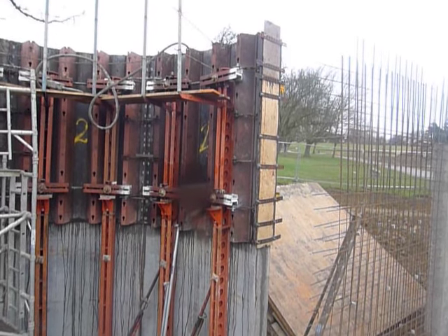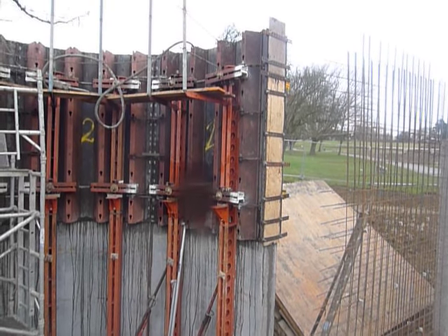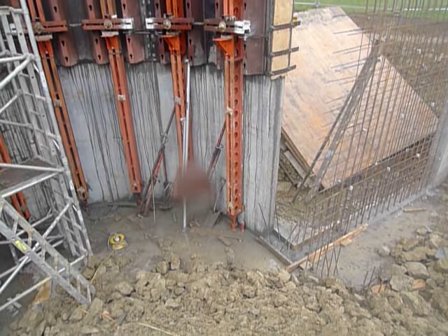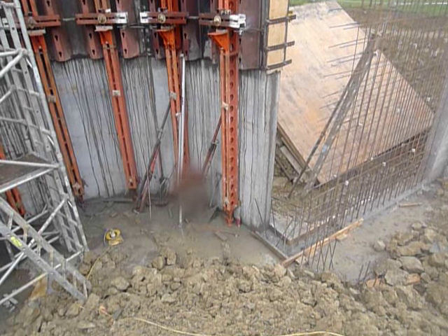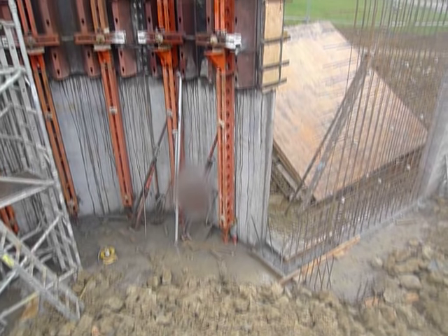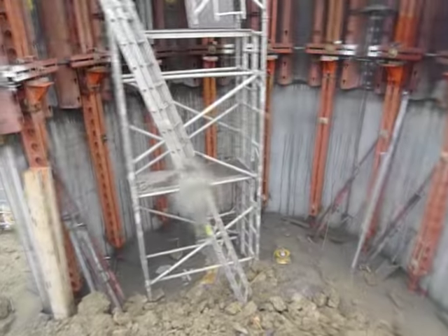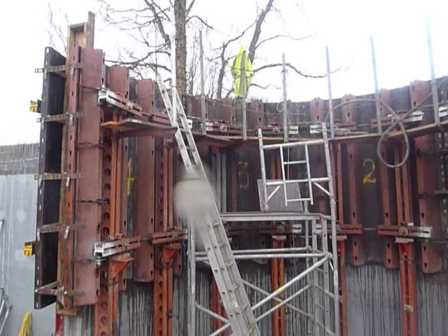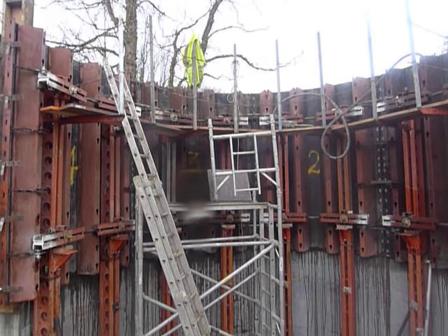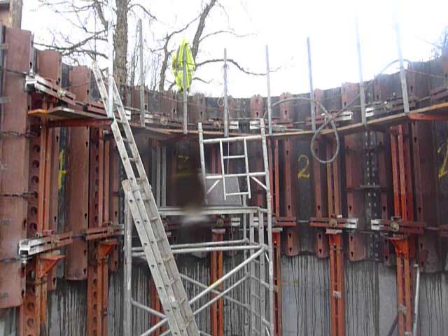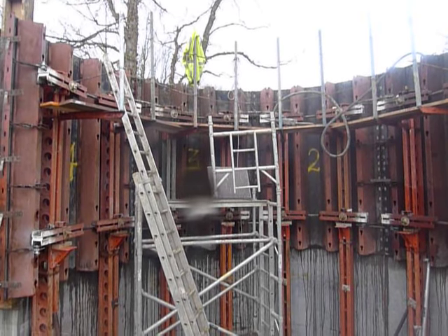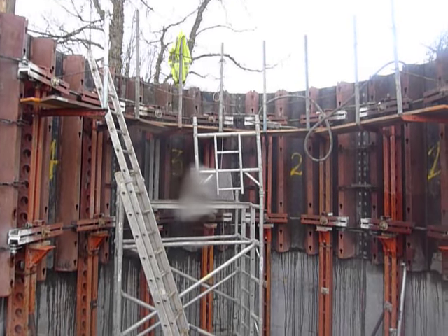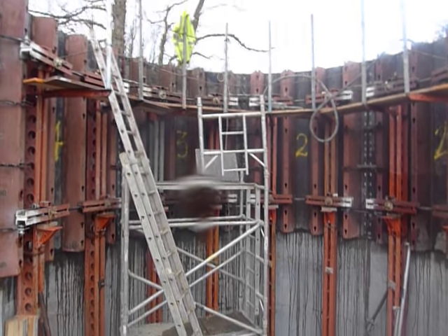And we clamp onto that, and we get our level by adjusting on, if you look at these RMD strongbacks, at the very bottom of them there is an adjusting system for the height. So they were all put to the correct height. That's very important, you get it to the correct height. And then ideally the shutter is all level, and it should work by aligning it in. Now it was lined in partly with plumb bobs, partly with me taking the odd reading on it. It wasn't too intense work for either carpenters or me. You know, it's quite practical at working.